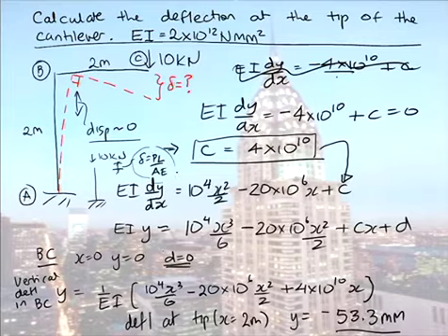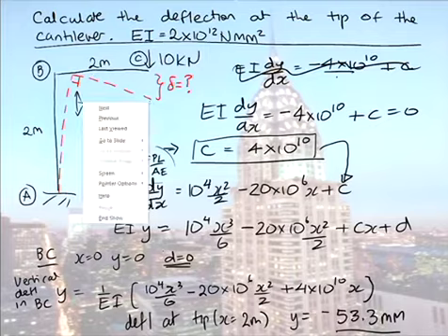If you put the area of the beam in, the Young's modulus in, and the length, you would find the displacement values you get in there are point something millimetres. So it's effectively negligible. So the deflection at this tip here, as I said, is a result of BC bending, curving, and a result of the fact that that corner rotates.